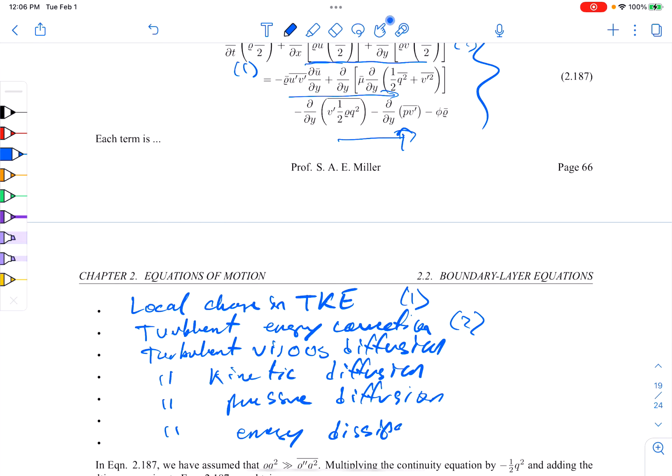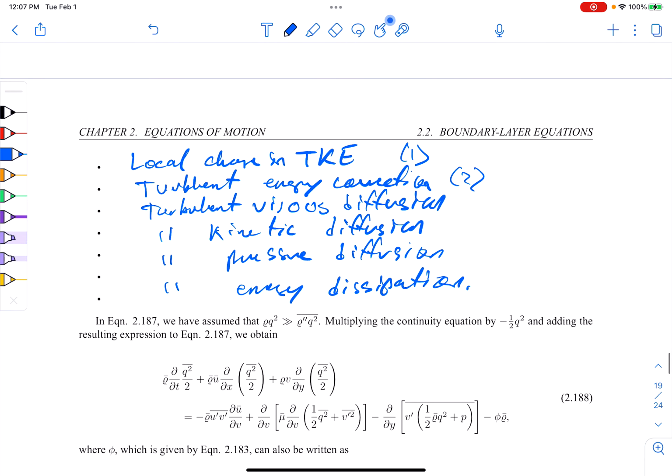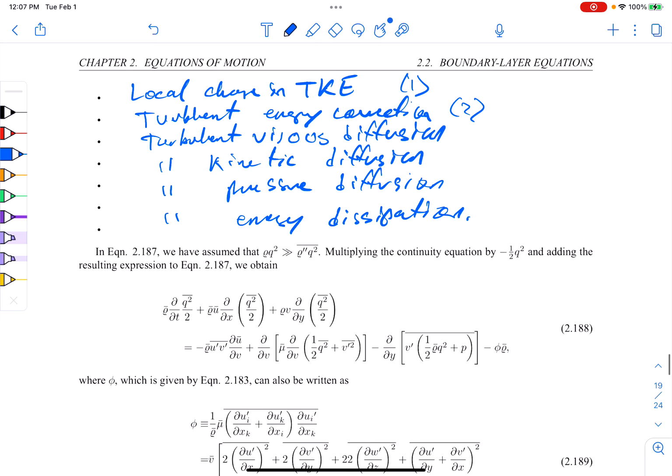So when you're trying to close compressible turbulence models, we're going to look mostly at compressible models in the class because that's what they're generally formulated for traditionally, and a lot of the famous models are that way. People actually reference the different terms in these equations and might even do a whole study and paper just to try and find good closure models for these particular relations and try and relate them to known variables in the base RANS equations like U bar and V bar. Okay, I think people are still copying that, so I'll leave that there.